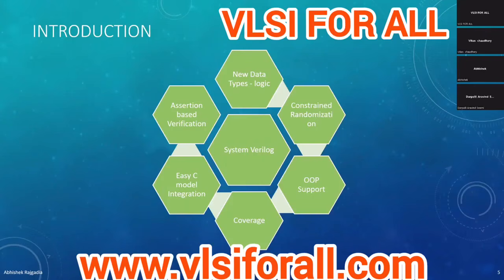Then assertion based verification. An assertion is basically a different kind of checker, which tells that if some events happen at the input of the design or somewhere in the design, what should be the corresponding output and at what point of time. Like in case of our adder, if A and B were both 1, then the output sum should be 0, carry 1. So that we can write in an assertion. If A is 1, B is 1, then we can say C is 1. So the assertion will keep checking every time whether this condition is true or not. If ever this condition is not true, it will flag an assertion. That is why we call it assertion based verification.